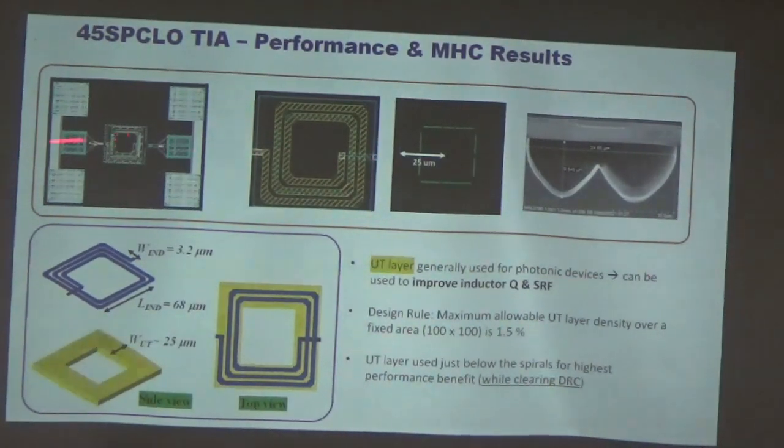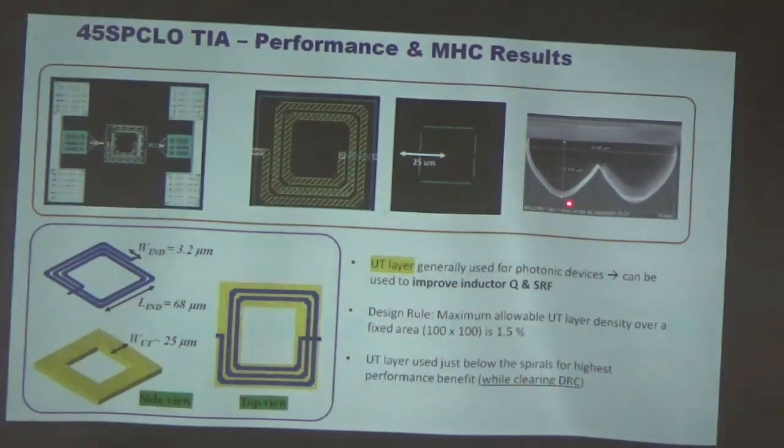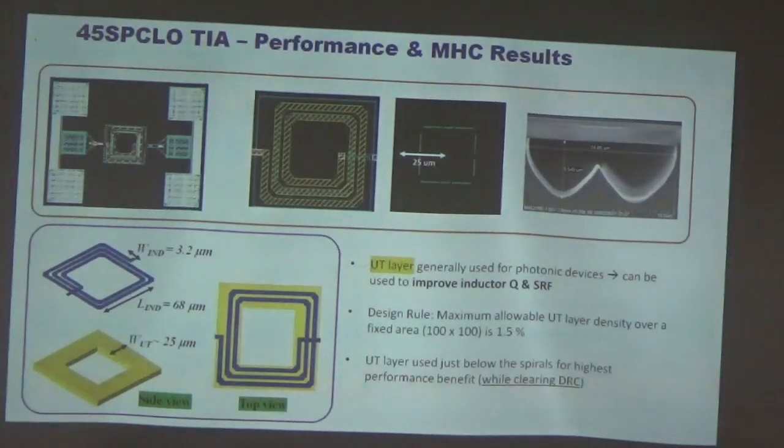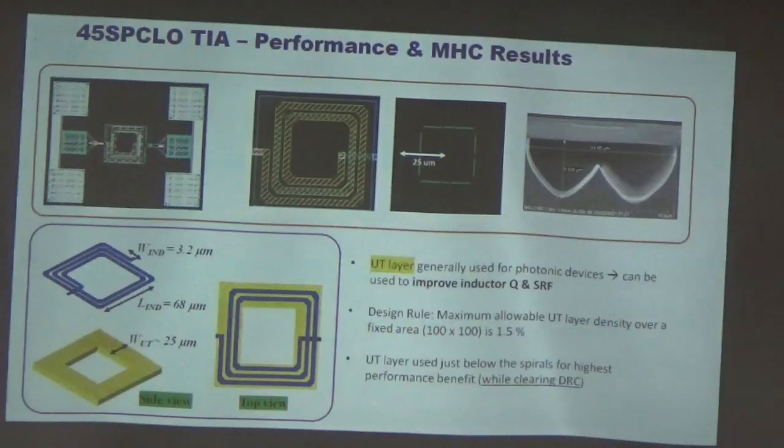The main idea here is we introduce some cavities in the inductors, because the silicon substrate is a lossy substrate, with very high resistivity. Most of your signal, the EM fields going through your substrate, gets leaked out because of eddy current losses.